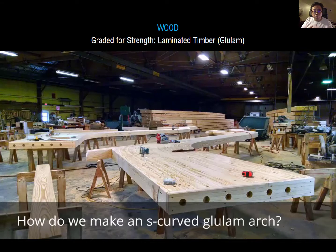Glulam is available for making curved structures. But how can we make bent wood? The wood should be steamed 1 hour per inch of thickness. If the Glulam is 1 inch, you have to steam it for 1 hour. But if you have a 3-inch thickness, you need 3 hours of moisture steaming to make the bent structure.